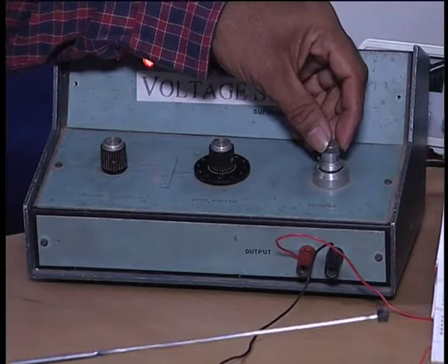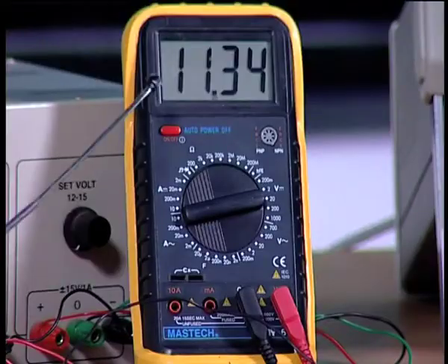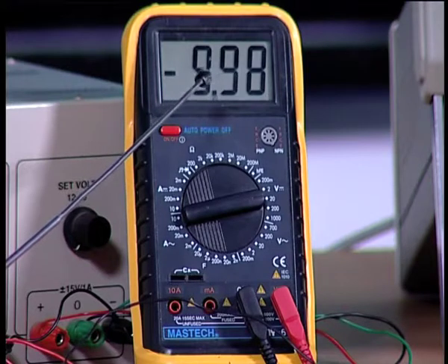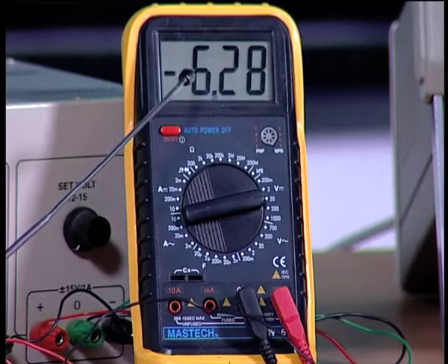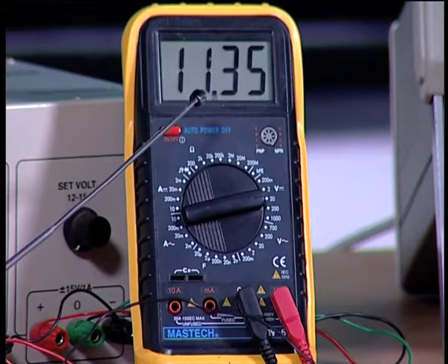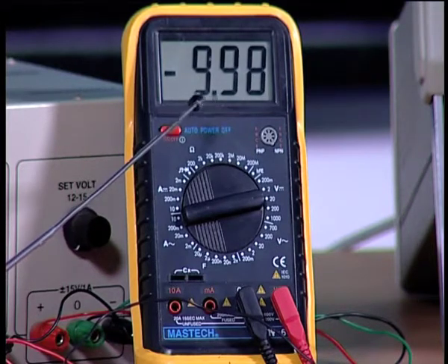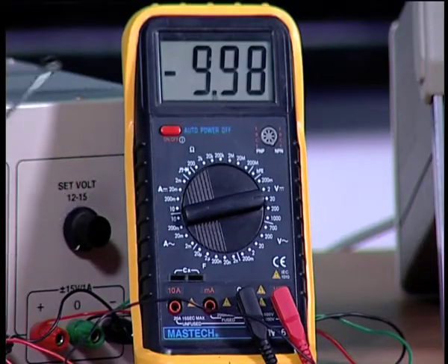There is another dial here which can vary continuously. So now I would like you to watch the multimeter as I keep increasing it. You find when I just move by very small extent, it has come to minus VCC. I again go back, you will find again it comes to plus VCC. I go back again, you would find it becomes minus VCC. So it is at this threshold that this happens, and if you measure this, it will be very close to 1.2 volts or whatever is the input at the positive input, that is at the non-inverting terminal.